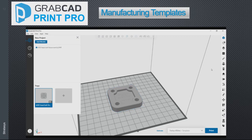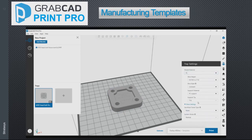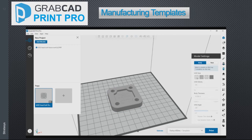So let's say that this customer wants me to build this part in polycarbonate. With a 13 thousandths of an inch slice thickness. And they've specified that they want sparse infill with a certain infill density and a certain body thickness.